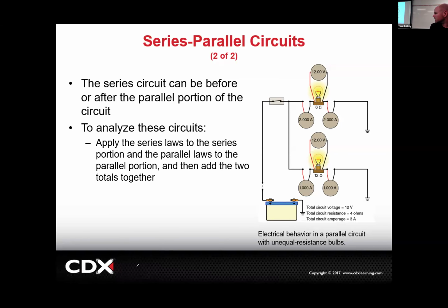So if I take this, although it's a good enough lesson because it looks like it's series parallel, because wouldn't you say this is the series? But it's only series if it has a load. So if I were to draw a bulb right there, now that would be a series parallel because there's a load in the series part. So if we were to do the series part traced, let's do it in this color, pink. This would be the series.